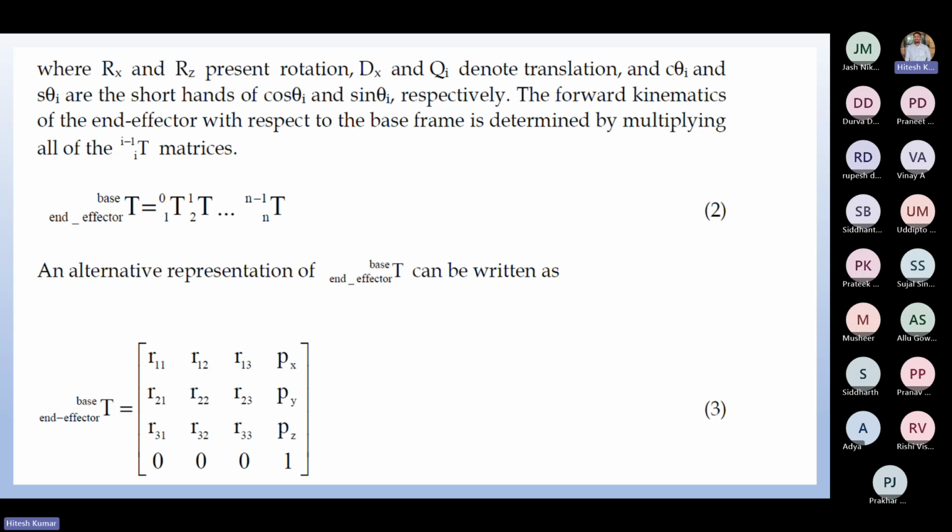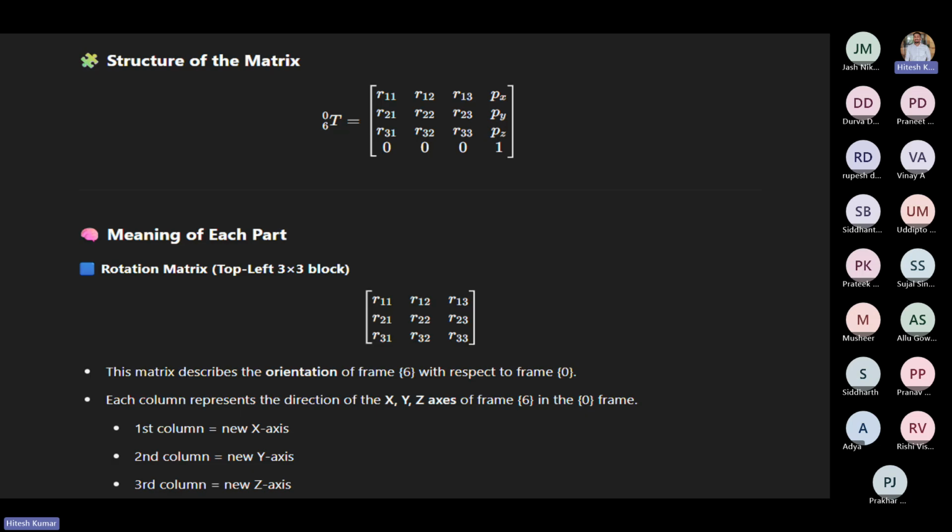Now R11, R12, R13, what are all these things, what does this matrix denote? We also have to understand what this matrix means. We multiplied, so what are we actually getting? What we are getting here is of great importance. See what it is: the first row, the second row, and the third row of R will give us the coordinates of the new x, y, and z axis.